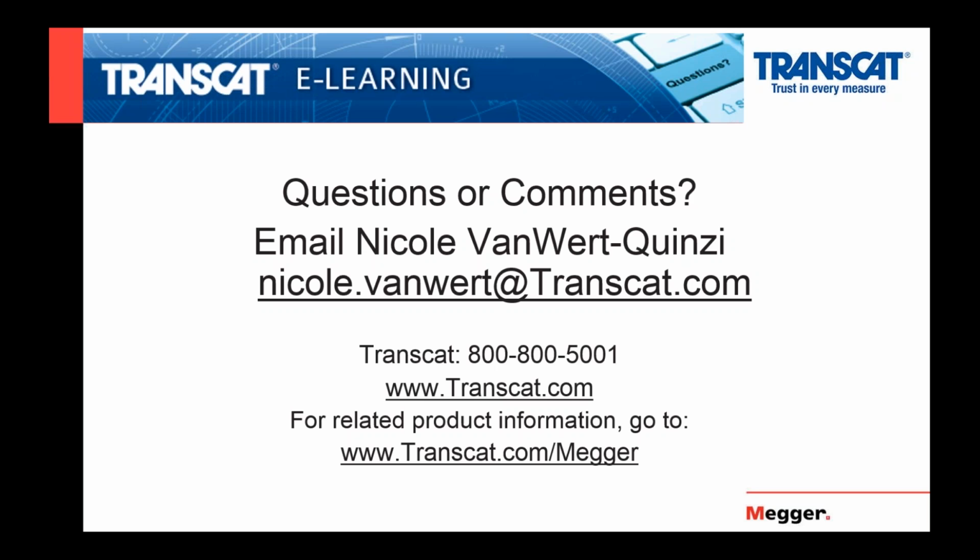Thank you. On VRLA batteries, when we see staining from acid, is it time to replace the batteries? When we see staining from acid? Yeah. I'm assuming that's probably on the post, so that actually would be an indication of a leaking post. So yes, if you see acid, I would replace that right away, because that acid can lead to ground faults.